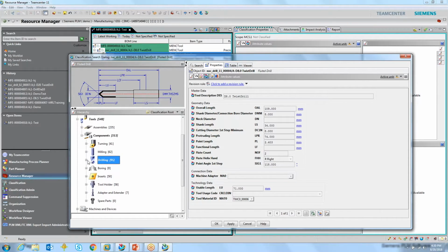There are certain ranges, and there's actually a couple different places for ranges. There's ranges for length as well as diameters. So you can actually give your tooling presetter guy a range that says, hey, this tool, because what you program it to is never the exact specific length. So you can give your programmer or your presetter guy a range that the tool has to fit within. And same thing for searching for holders of that sort.